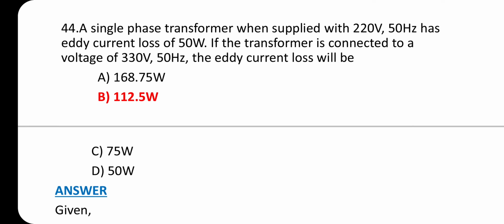Question number 44. A single phase transformer when supplied with 220 volt, 50 Hz has an eddy current loss of 50 watt. If the transformer is connected to a voltage of 330 volt, 50 Hz, the eddy current loss will be. Answer is option B, 112.5 watt.